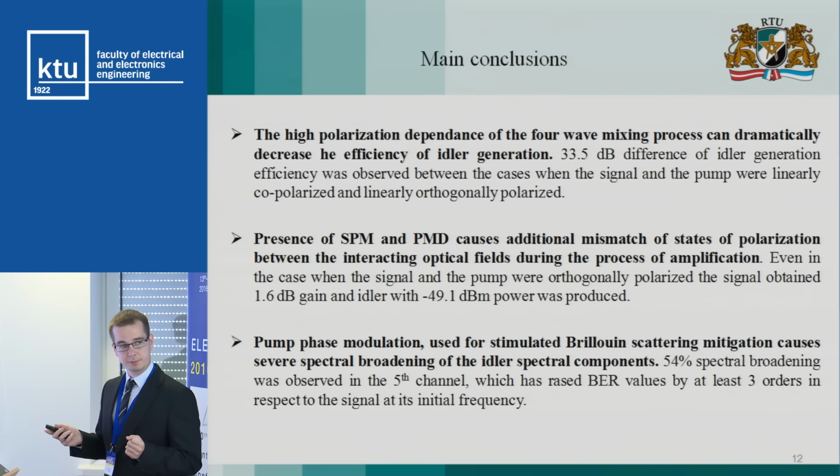And finally, it was found that a pump phase modulation, which is used for mitigating stimulated Brillouin scattering in parametric amplifiers, results in broadening of the idler spectral components. This broadening has resulted in increase of beta ratio values, by at least 3 orders in our case.